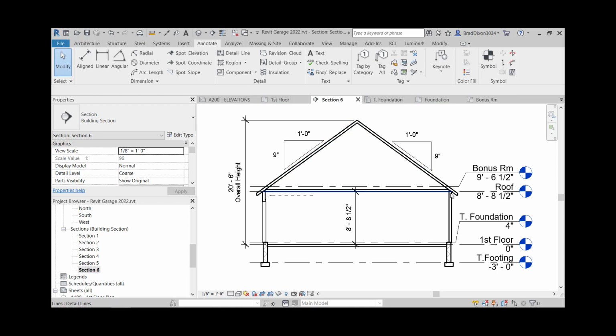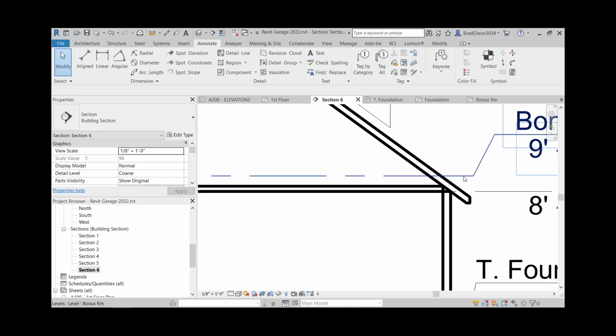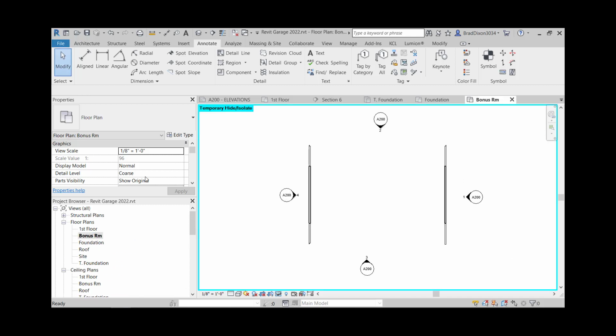Basically, to see these walls, I either have to turn my underlay on, or I need to have the view range go down past, in a negative view, down to here. So I'm going to start out by trying to just use my underlay with that.